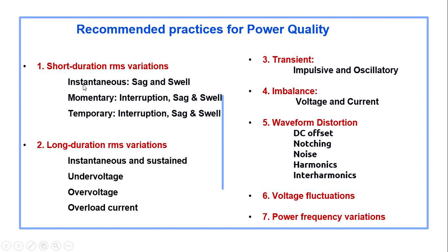In instantaneous, sag and swell. Sag means your voltage is dropped and swell means your voltage is increased. Next one, long duration RMS variation. It is divided into further parts: instantaneous and sustained variation, undervoltage, overvoltage, overcurrent.